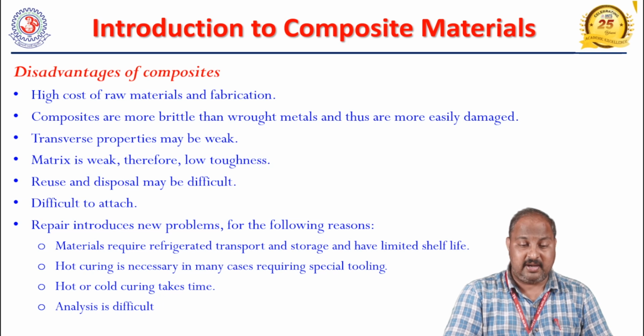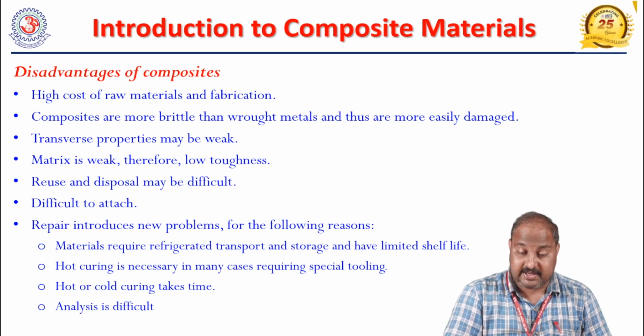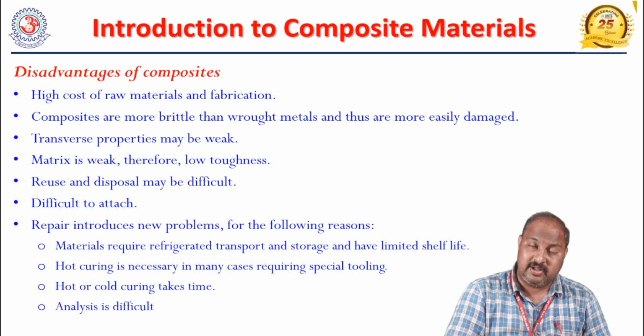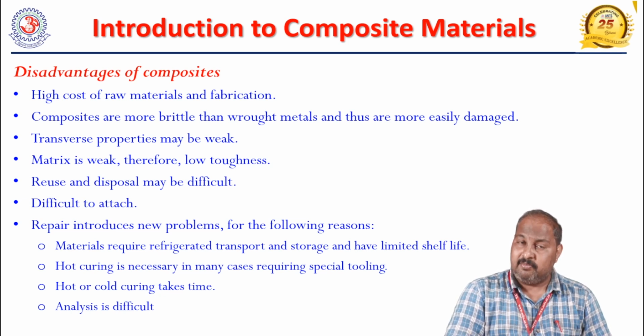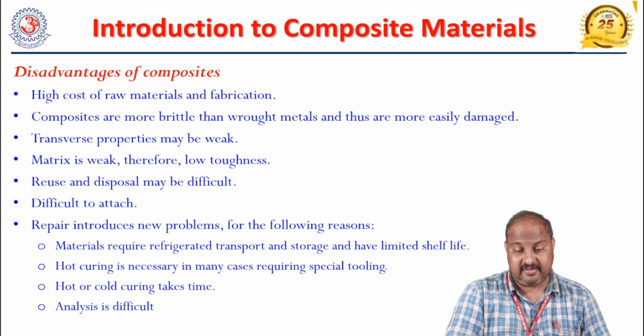And repairing composite material components introduces some new problems, because it is limited for some reasons: materials require refrigerated transport and storage and have limited shelf life. Hot curing is necessary in most polymer composite cases, requiring special tooling. Hot or cold curing takes time.